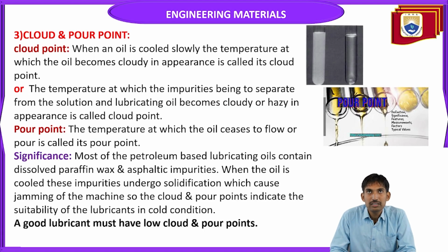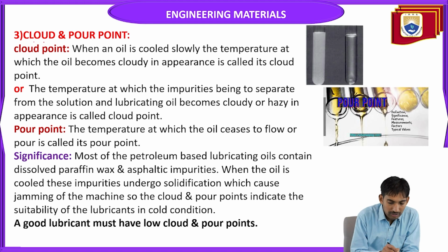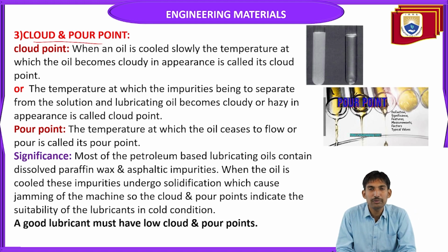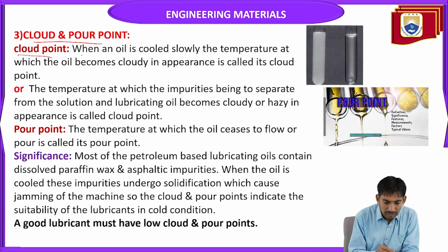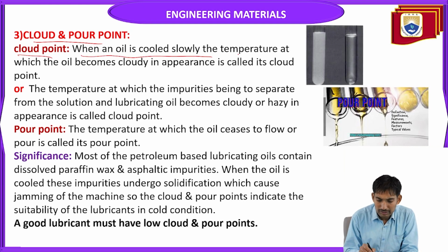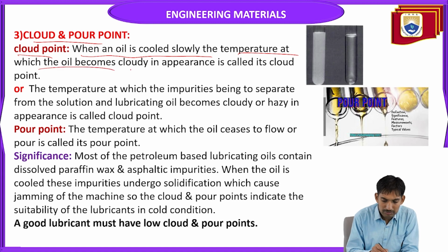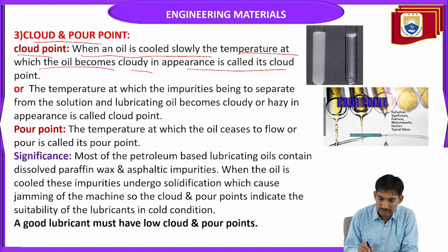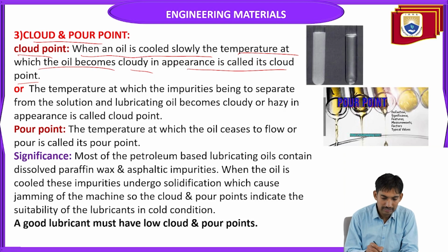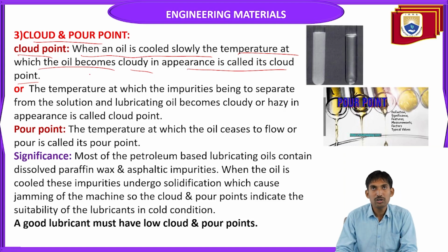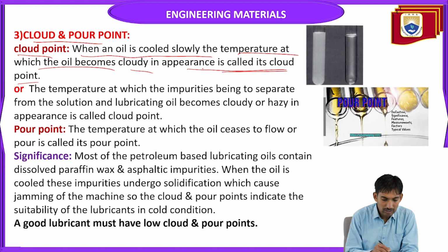The next property of the lubricating oil is cloud and pour point. See, cloud point. When an oil is cooled slowly, the temperature at which the oil becomes cloudy in appearance is called cloud point.